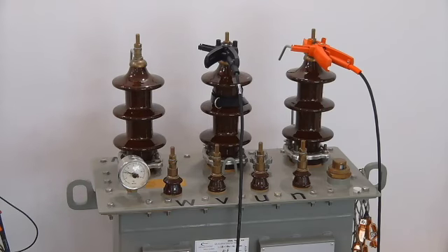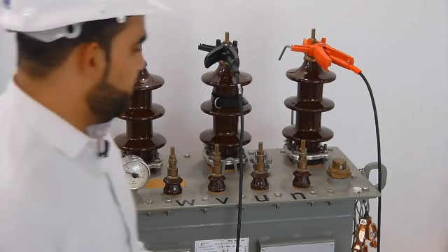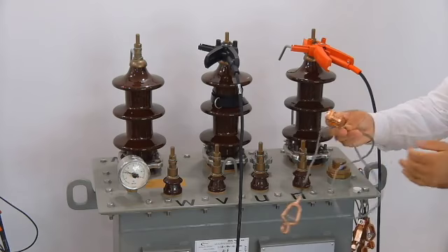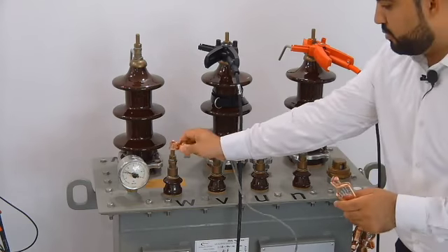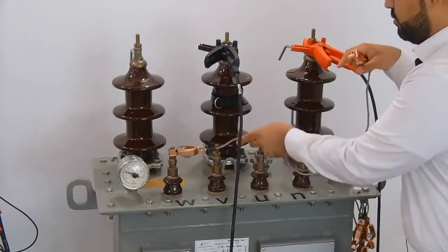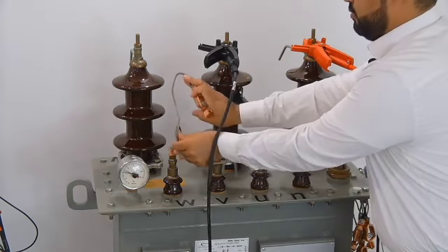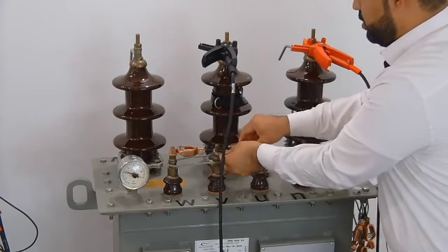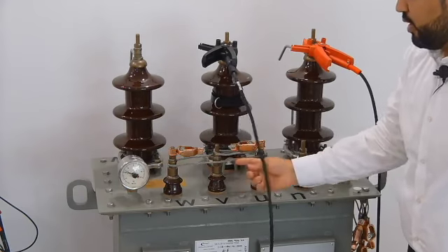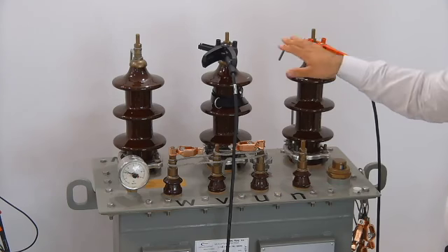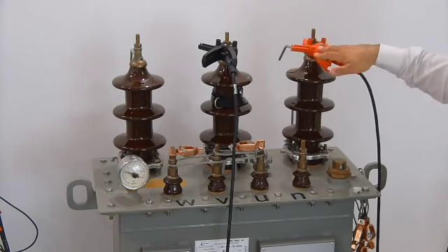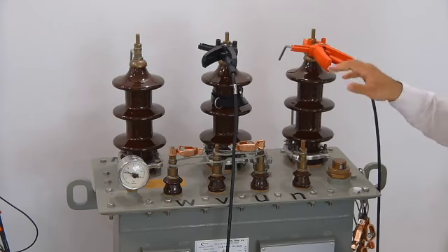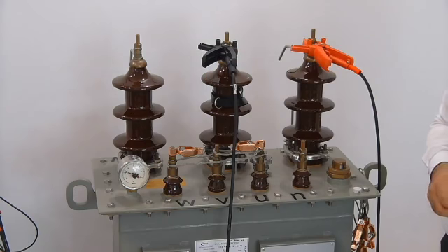I just need to apply the short. So I'll be using a shorting lead. This needs to be tied very well so I can ensure proper current flow between the three phases while I'm injecting current between the two phases. I will be switching these two clamps to the next phase and to the third phase one by one, and I will do it with you together. We go now to the software.